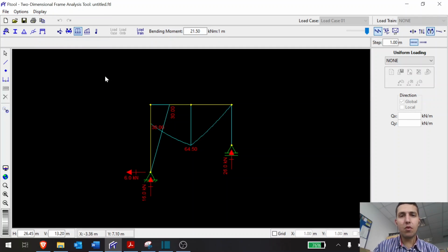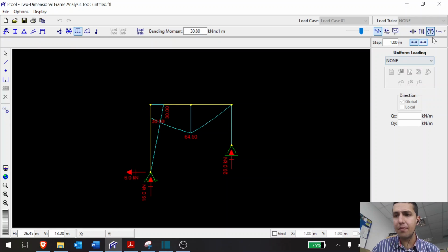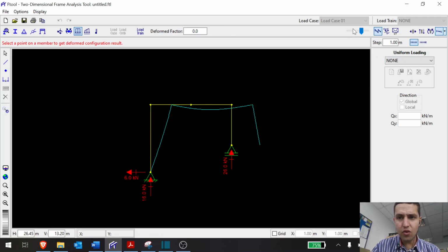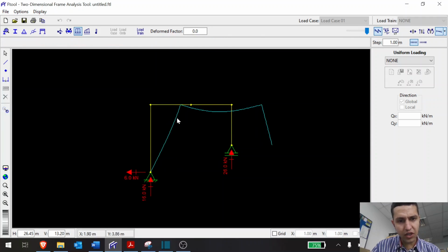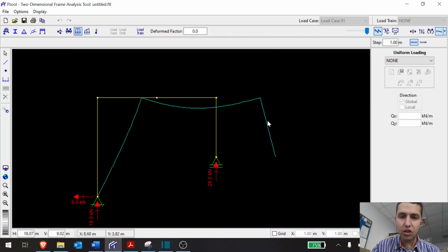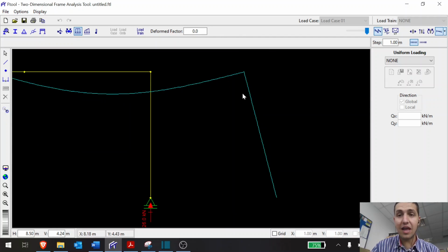Now that you're done with the model, you should definitely play a little bit with it. So if you look at the bending moment diagrams, this is the numbers we get. So we should have tension on the right on here, and then tension below here. And this bar shouldn't have any bending. If you go to the deflection, you can see that straight away. So tension on the right in this bar, and then tension below in this bar. And this bar is not bending, it stays flat.